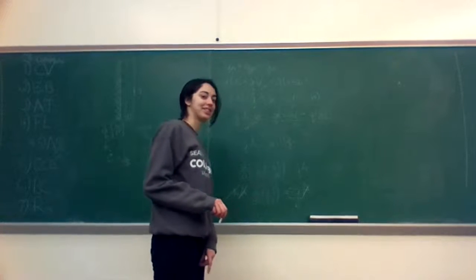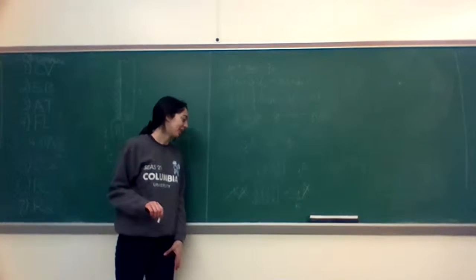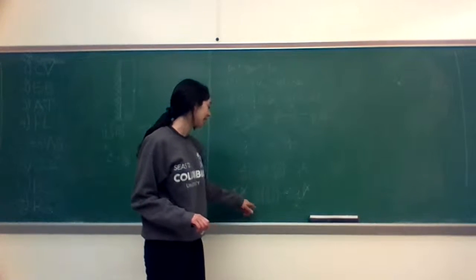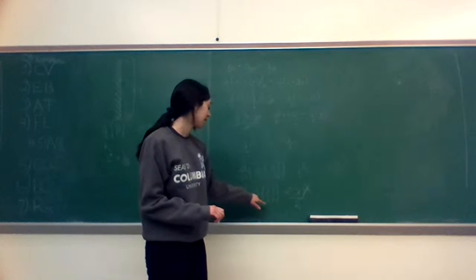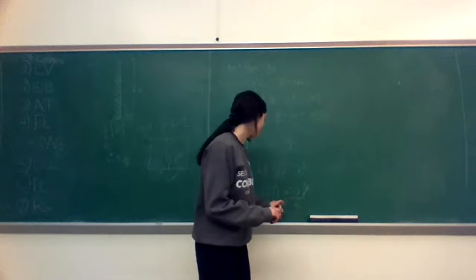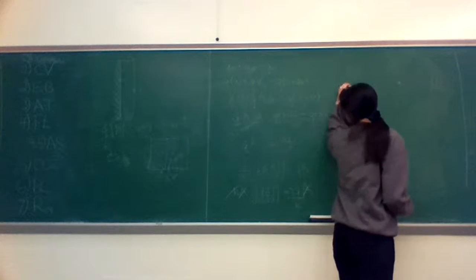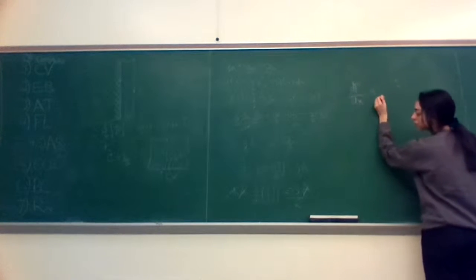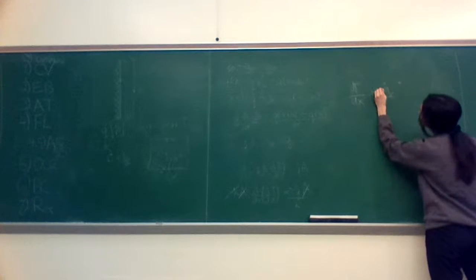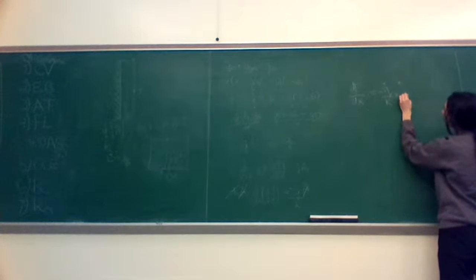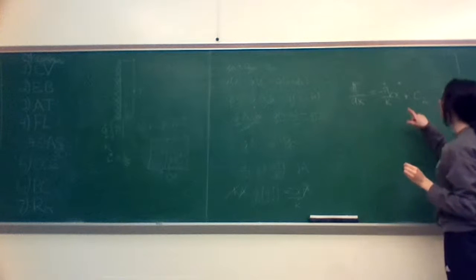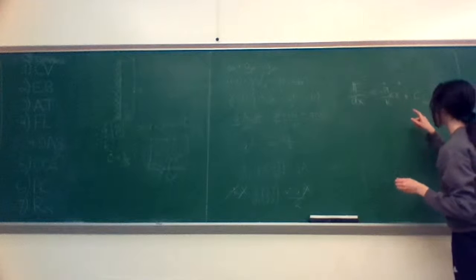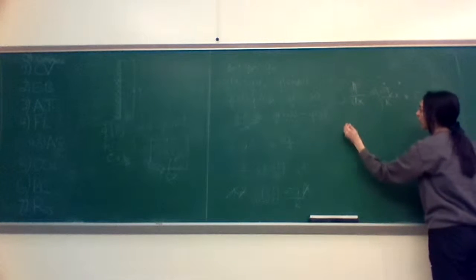Yeah, q and k are both constant. So because we have uniform energy generation and conductivity is a constant, when we take d/dx of this expression, we know that we have a constant, meaning that when we integrate, we get a term that gets multiplied by x. Then we add on a constant from the integration because we don't have limits yet. If you were to take the derivative of this again, you can see that it turns into that. Then from there, we have one more antiderivative to take, right? So we do it with respect to x, we have dT.